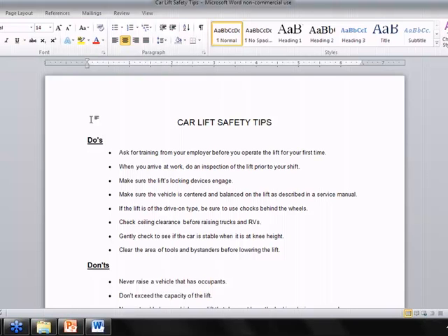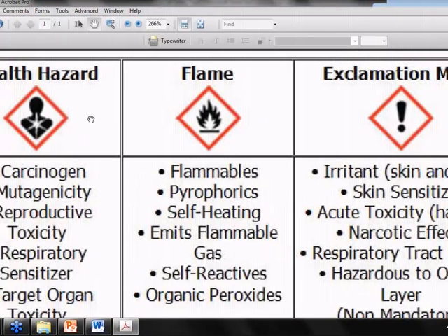However, there's a separate regulation called the Community Right to Know Law, so that any chemicals that are over thresholds, it's usually 500 pounds for everything except for petroleum products, that's 10,000 pounds, has to be submitted every year by March 1st, a list of those chemicals that are over that either 500-pound threshold or 10,000-pound threshold for, say, oil. And that has to go to the DEP, and it also has to go to your local emergency planning departments, like the fire department, the police department, and then there's also a local emergency planning coordinator that needs to go out by every March 1st.